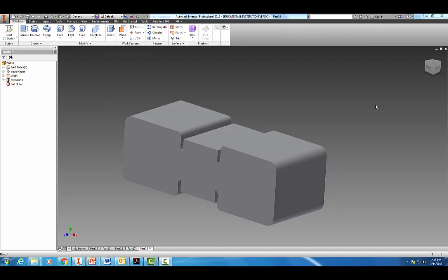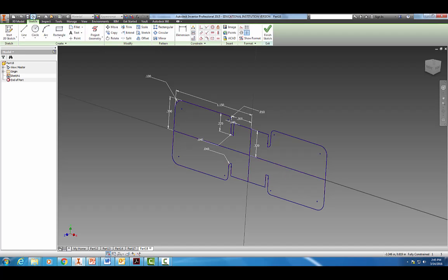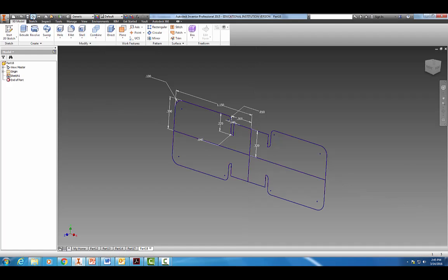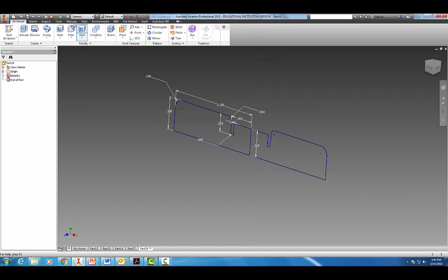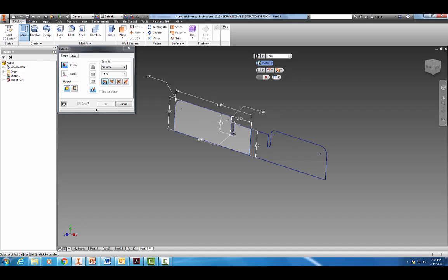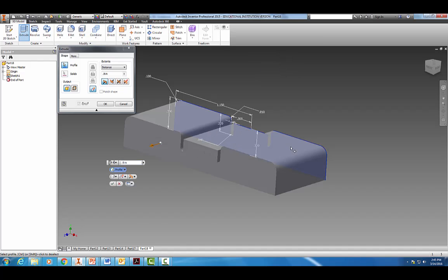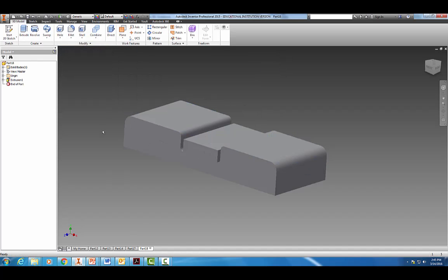I'm going to show you another way to do this, if you've been having trouble following me. I'm going to do some edit undos here. Hopefully you were able to get this mirror part in here. So now I'm going to finish sketch. I'm going to extrude that face and that face. I'm going to hit OK. So we got half of it.